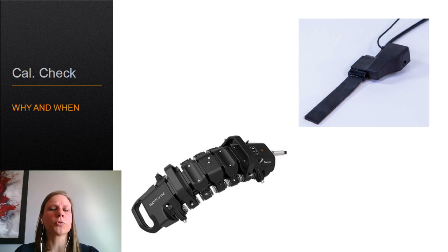If you are working at multiple frequencies, two frequencies, that means 256 channels per probe to manually validate when you are checking your calibration or when you are checking that your probe is functional. So that takes time and there are risks. You can scroll through all the different channels and at some point you're just going too fast and you let one dead channel slip and then you're screwed for your inspection. So that's why we thought that the CalCheck feature would be very interesting, because we're coming with bigger probes, more channels to have larger coverage or more sensitivity. So that's the way things are going. So might as well make it easy to use.